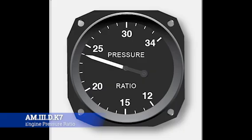All right, so it measures that pressure ratio of the exhaust gas pressure at the turbine exit and the air pressure at the compressor inlet. So it's looking at the inlet, and it says, hey, look, it's at 1 atmosphere, but on the back it's 10 atmospheres. Your EPR ratio is 10. Makes sense? All right, so it's used to gauge the thrust output, particularly in turbojet and turbofan engines, reflecting engine performance. You get it by taking the turbine discharge total pressure and simply dividing it by the compressor inlet pressure. Now, higher EPRs generally indicate a greater thrust, as it reflects a more efficient compression and expansion.